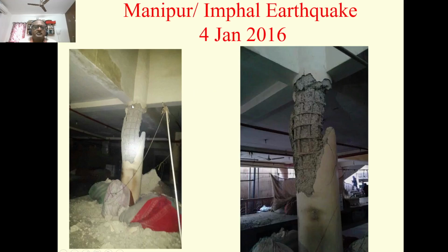And these are all the other pictures taken in Manipur and the Imphal earthquake. Very similar. Initiation is due to top bending moment. Of course, for various reasons, it continues. Not like the previous cases, here it continues up to the middle.